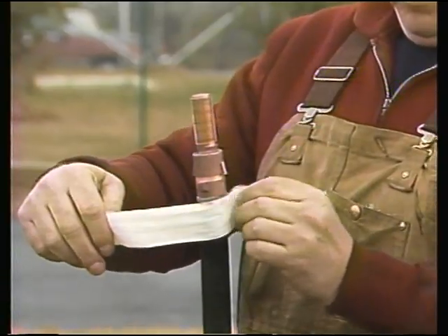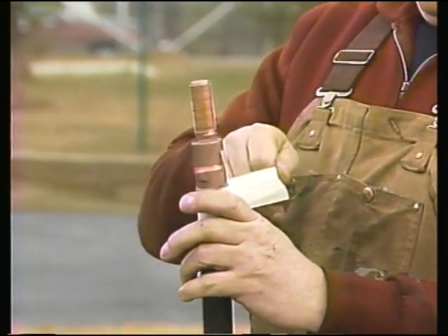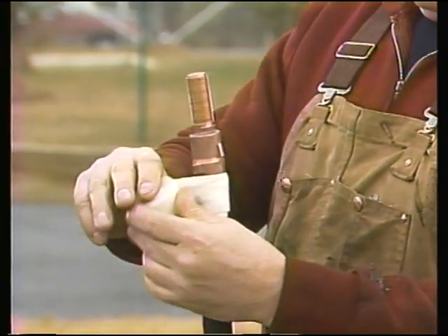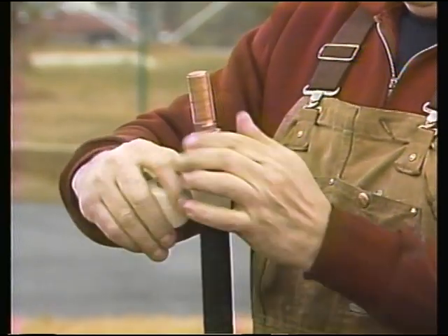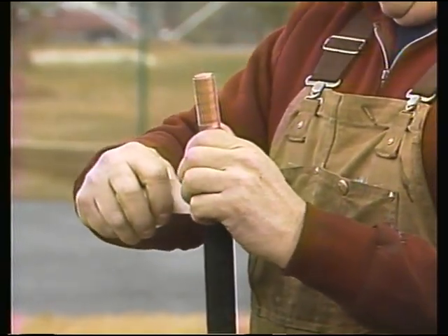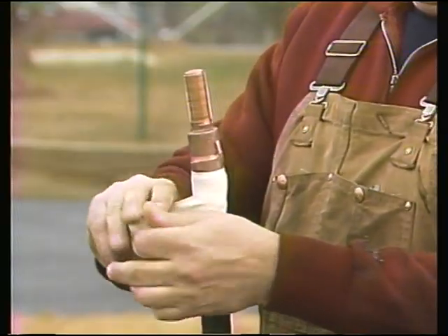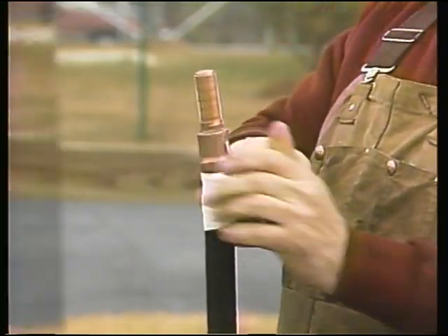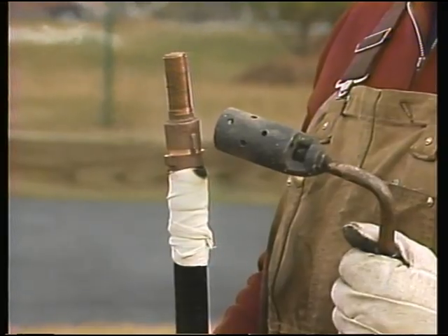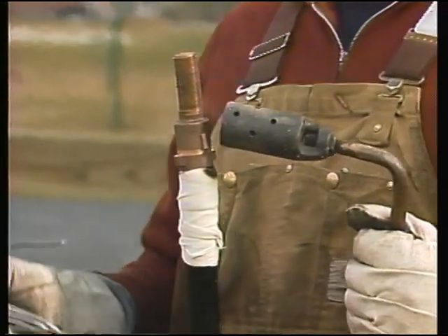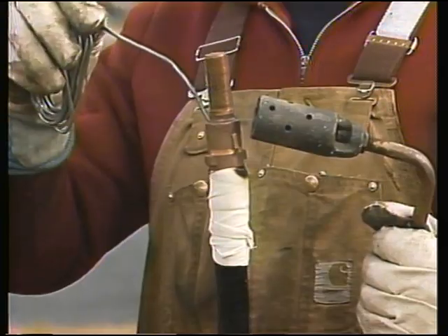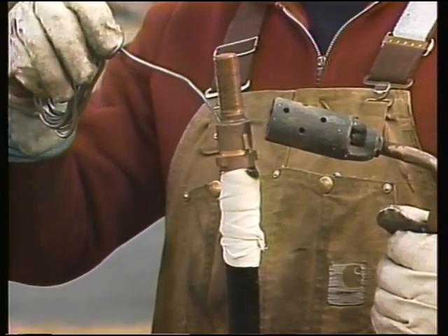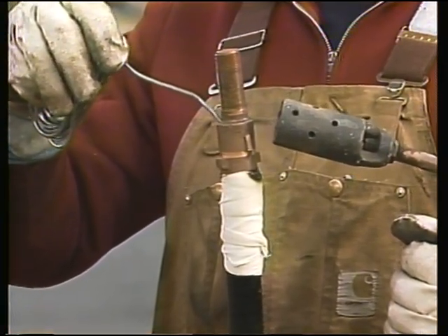The workman then puts the connector in place and wraps a fire-retardant cloth around the bottom of it. He wraps the cloth around the cable in the area between the connector and the cable insulation. The cloth will stop the melted solder that will be used to install the connector. Then a torch is used to heat the connector. Wire solder is fed through the top of the connector through openings called soldering holes.